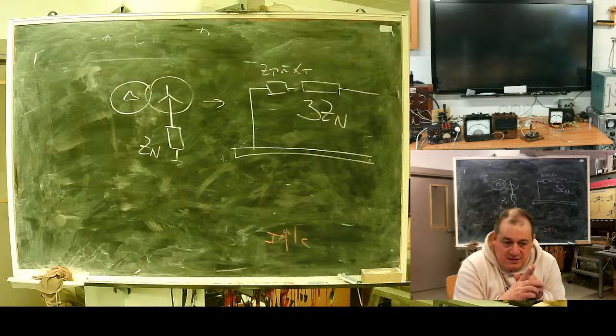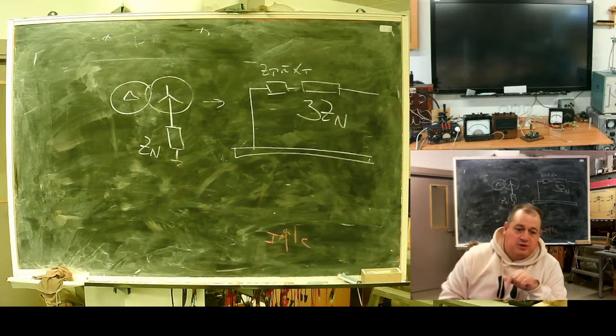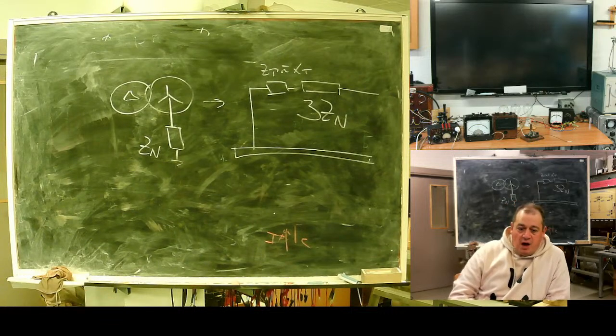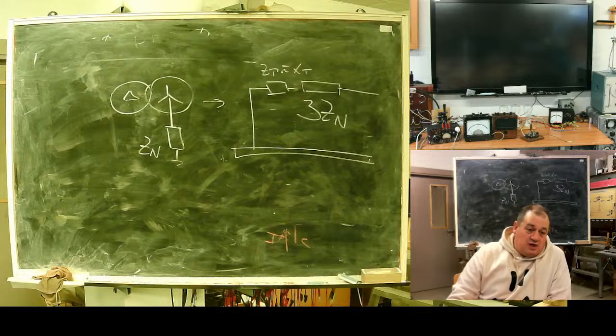Do not rush. Do it all meticulously, because these mutual inductances are a serious factor starting from 110 kilovolts. The higher the voltage, the more serious the effect of line-to-line coupling. Do not ignore it. Okay, I'm out of time today. We'll continue with why I'm talking about all of this.